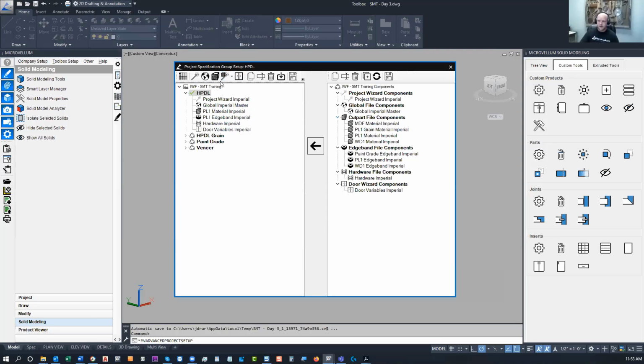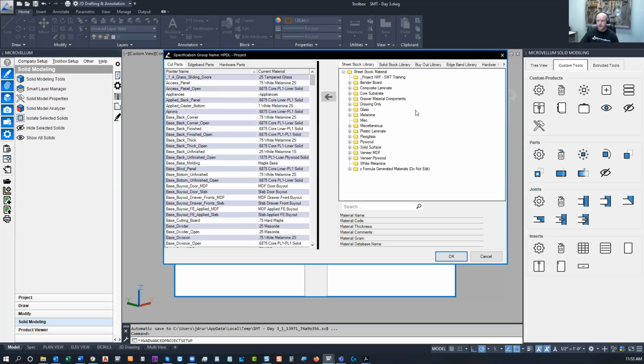Yeah, same thing. First, start off in your material file by adding that material into whatever category it's going to fall into. If it's something that you're just trying to account for, maybe it's a bar rail foot, you're going to add that into your hardware. If it's a buyout item, maybe it's a metal strip, a flat bar, angle iron, whatever it is, you can add that into your buyout library. And then depending on how you have your properties set up, whether that's going to be a per each kind of item or a linear foot kind of item, you can set that up.